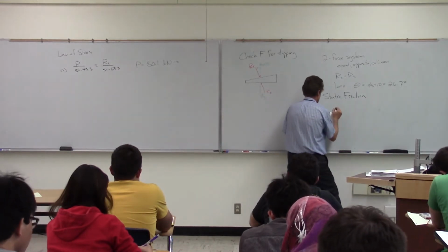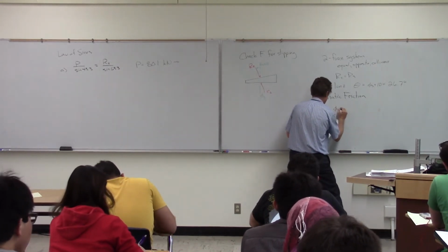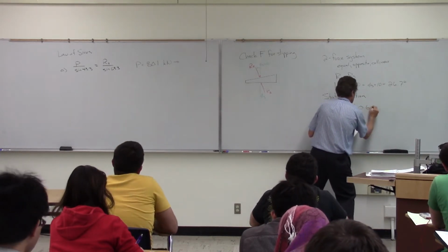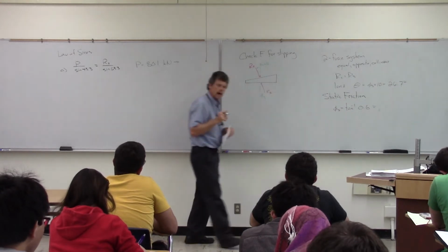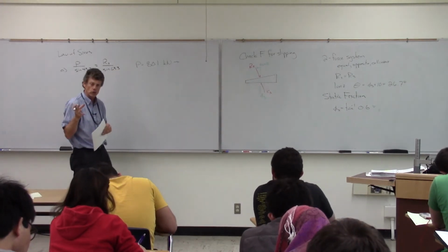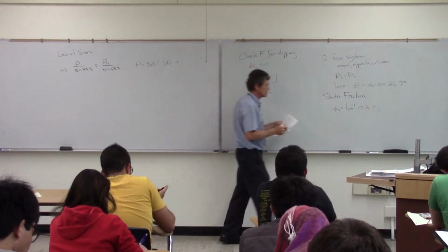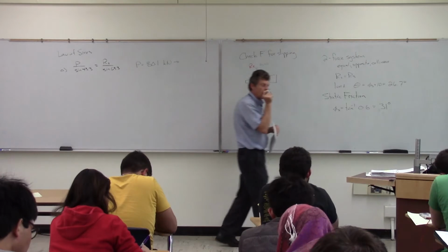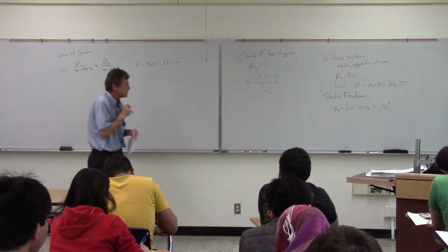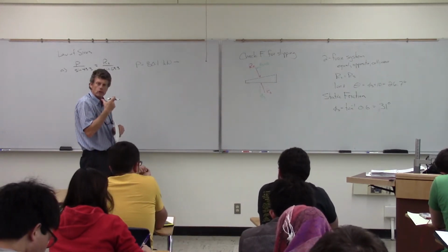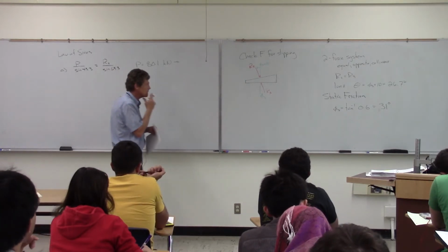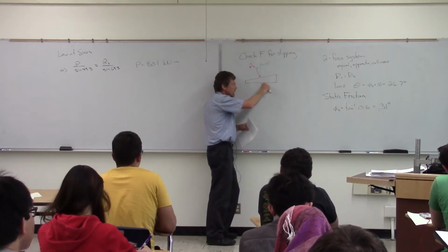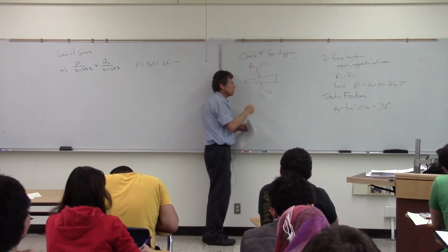So what we'll find is that's going to be the coefficient of friction down there, which is now 0.6. And that says for that block to start moving in relation to the concrete base there, it has to achieve an angle of 31 degrees. So what we're saying then is for this thing to start moving, it's going to see a friction force now, angled out